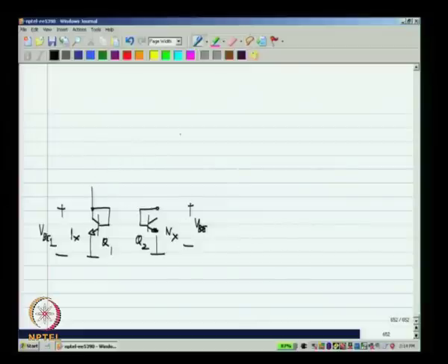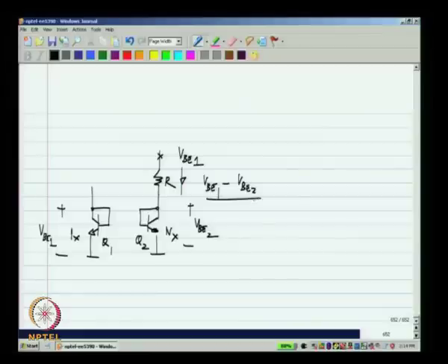So, we have VB1 over there and VB2. If I connect a resistor here and the voltage here happens to be VB1, then clearly the current in this will be VB1 minus VB2 divided by R, which is Vt by R times natural logarithm of n.